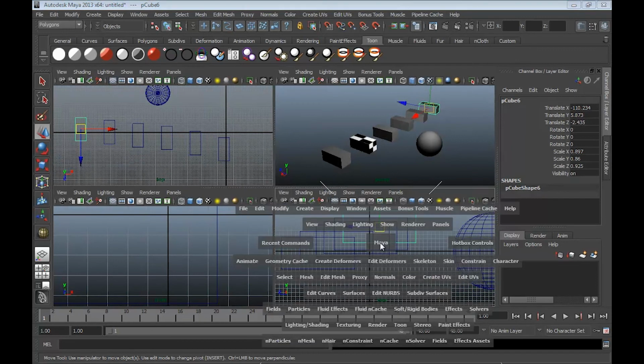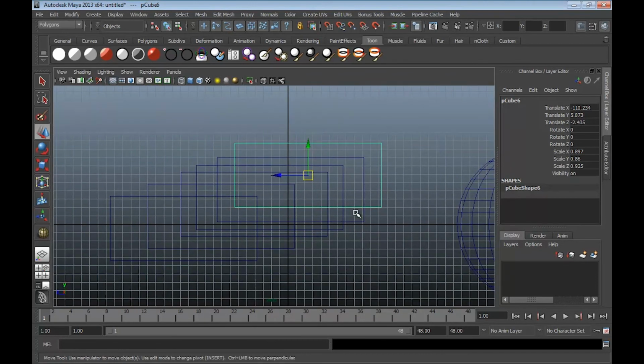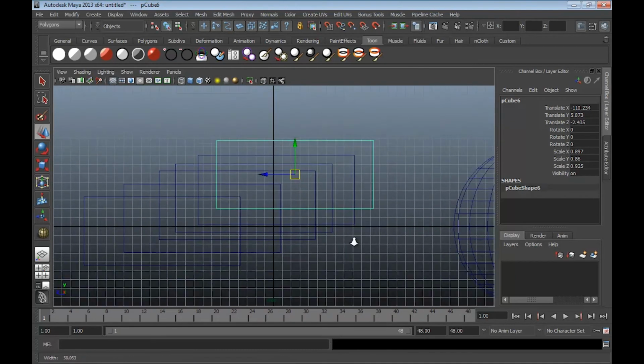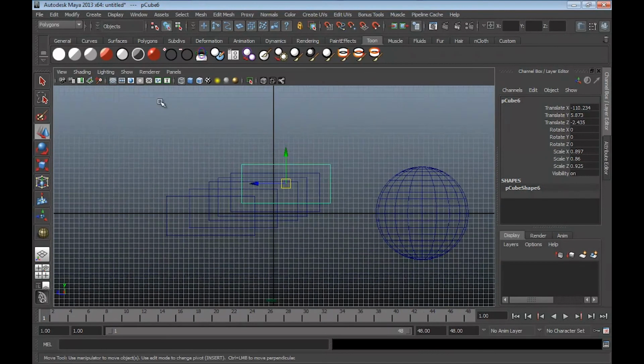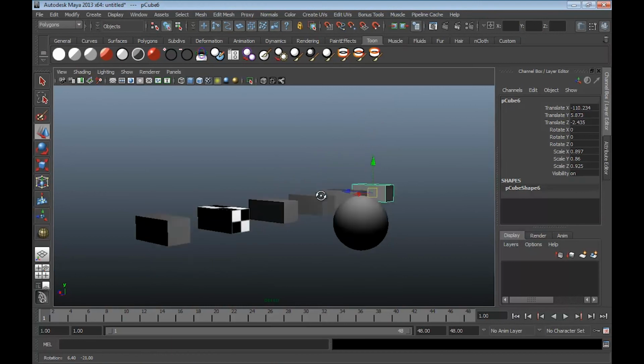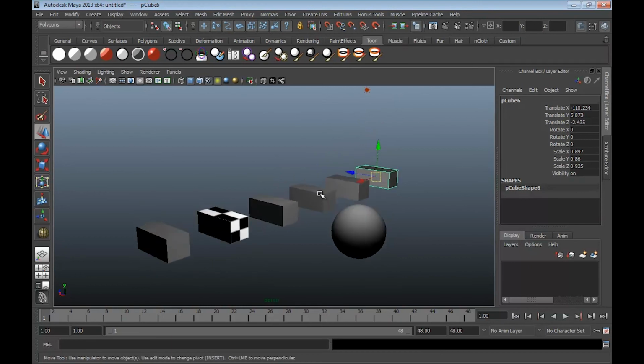Navigating them is its own thing. It's very easy. It's very similar to navigating a perspective view, but there are a few primary differences. You're still going to hold down the Alt key. Because it's an orthographic view, you cannot tumble it. If you are coming to this from 3ds Max, no, there are no user views, or such as Blender, where you can just rotate any old view and make it orthographic. You can't do that here. Orthographic views are always looking down one of the primary axes. But you can hold down Alt and middle mouse drag to pan, and right mouse drag to zoom in and out. So those are your navigation buttons for an orthographic view.